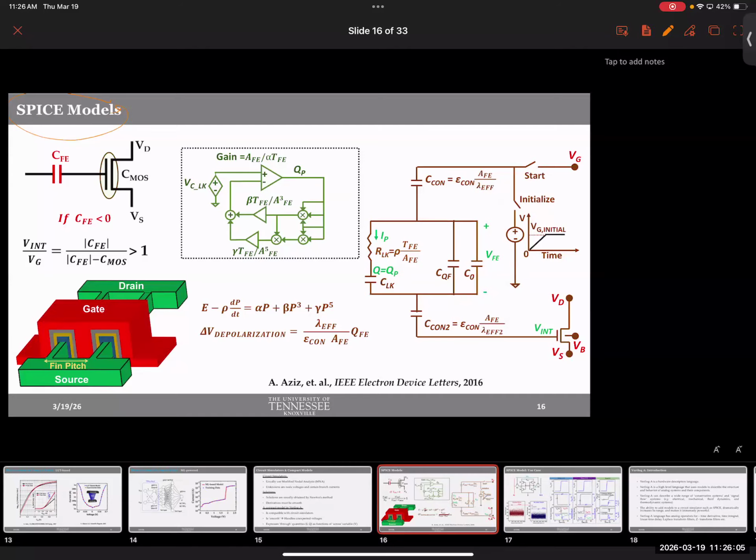But before that, I wanted to start with a different example that is not Verilog-A, just to show you that there are other options out there. Verilog-A is not the only option, right? Although it's the preferred option nowadays. So this is one example of a SPICE-based model. You mentioned that you have used LTSpice or some other versions of SPICE in different parts of your career, but maybe not all of you have used HSPICE. Typically, the model that I'm showing you here was implemented in HSPICE. But there are other versions of SPICE which are also used to develop models, like, for example, WRSPICE, and all sorts of other versions.